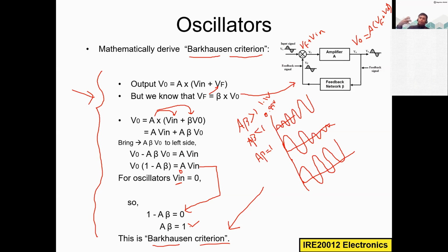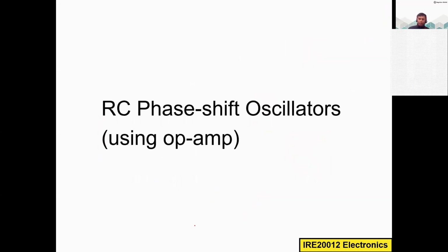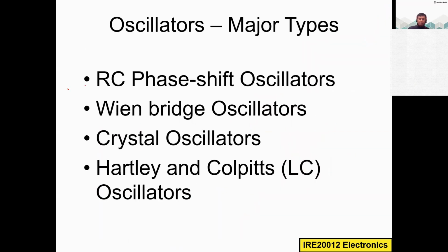You can apply the same conditions in any kind of oscillator, like we are going to see many different types of oscillators later. In each oscillator, you are going to use different components to design the circuit, but regardless, it must follow these conditions. Then only we can get the standard or constant value at the output. Otherwise, the oscillation will die or it will keep increasing indefinitely.